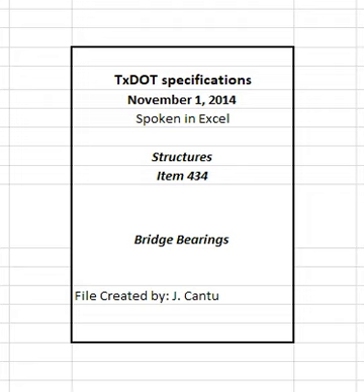3.2.2 Testing and Acceptance. Test a minimum of 10% of the sliding elastomeric bearing assemblies to a compressive strength of 2250 psi or a stress approved by the engineer. Provide calibrated equipment per ASTM E4 for this compression testing. No tested sliding elastomeric bearing may show visible damage to the PTFE or stainless steel surfaces, nor evidence of bond failure between the PTFE faced steel plate and laminated elastomeric bearing pad, steel laminates and elastomer within the laminated elastomeric bearing pad, and steel plate and PTFE.